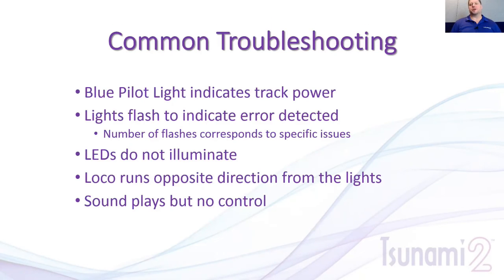Most of you guys are familiar with the CV reset. CV8 equals 8. Cycle the power, the lights flash 16 times, and that's your indicator to let you know that the reset has in fact taken place.